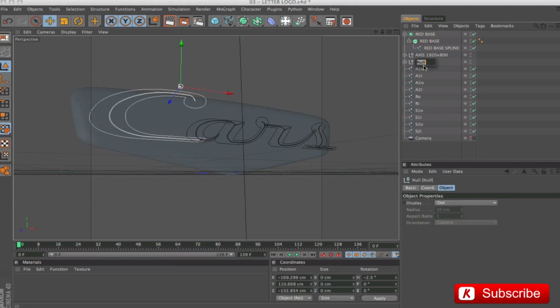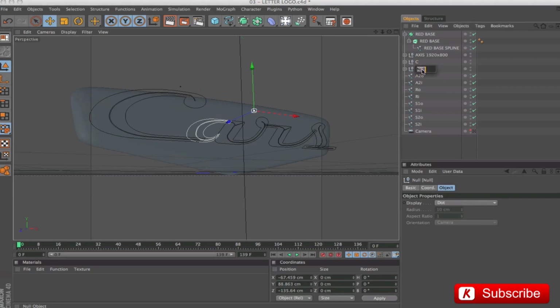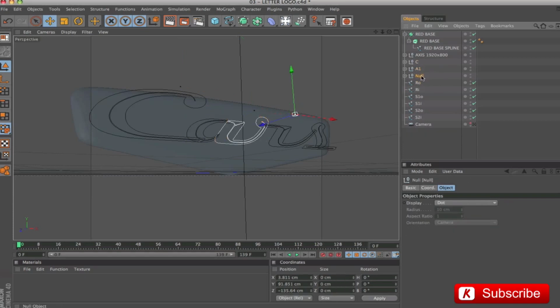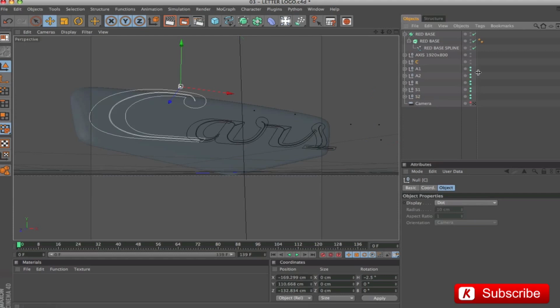Organize and group the letter splines of the logo, in order to work on the logo gradually, letter by letter. As we can see, the logo is made up of open paths, because the Loft NURBS technique works well only in this way. Okay, we disable all the layers and work only on those that make the C letter.